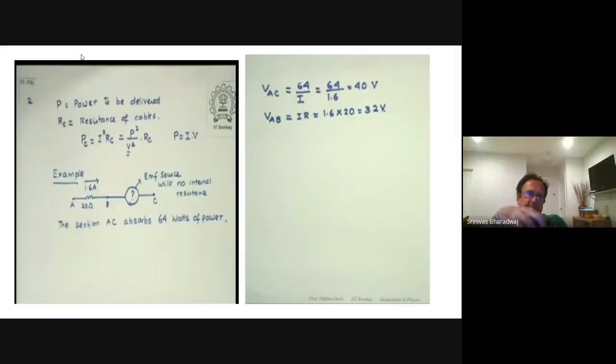You connect the voltmeter in between the two points and it tells you the potential difference between them. But the voltmeter will have its own internal resistance, sometimes a battery, and it can never completely avoid using some of the current in the actual circuit.